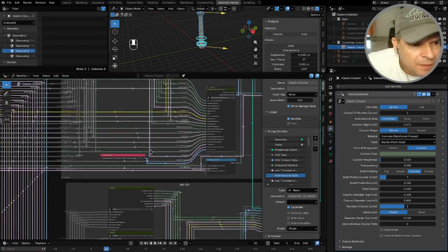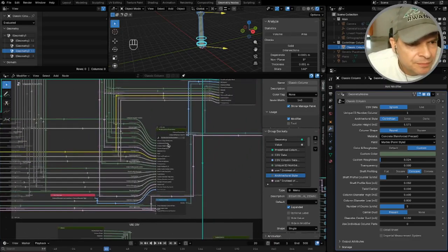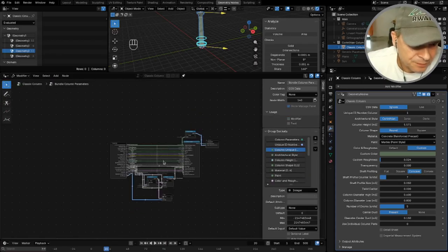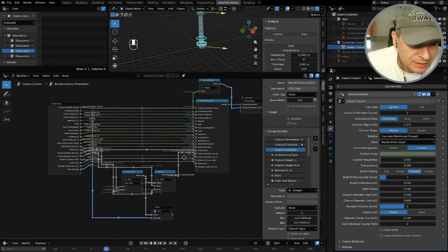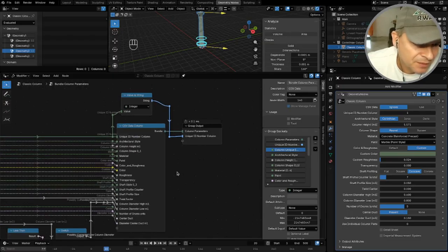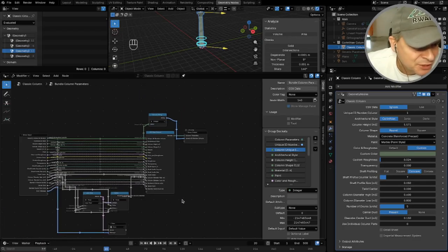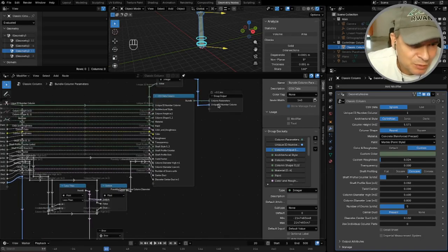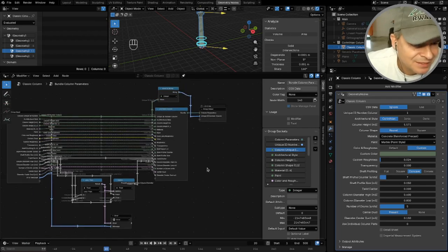Yes, so then from the gizmos we go into the data, where the data is condensed to a single bundle, which is done here. You can see that not everything is put in a bundle, because strings are not yet able to be collected in a bundle. So you can put anything in a bundle except strings, which is a bit of a shame, because there are some strings that I also would like to put in the same bundle. If that was possible, I would have had only one bundle in this place.